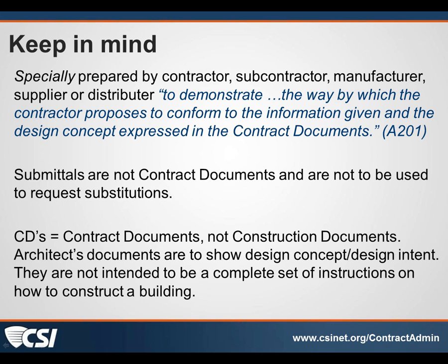That's a misconception that I run into a lot, contractors and owners thinking that the set of documents that we put together is an instruction manual like you would get when you go to a model shop and you buy a model airplane or whatever it is, and there's the instruction manual in there showing you how to put the pieces together and the sequence to do it all. That's not what contract documents are. That's not what the documents we prepare are. They're not what they're intended to be. The contractor is supposed to be the expert in construction and how to put it together. We are responsible for the design and the design intent, the design concept.